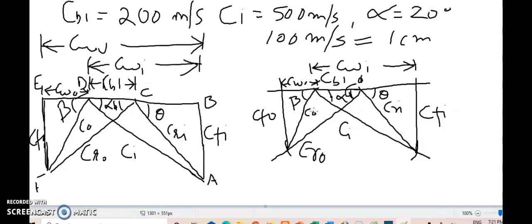So now we have all the data of the velocity triangles, inlet and outlet both, and such a method is known as construction method. By knowing all the velocities we can have blade efficiency, stage efficiency. Then obviously for the stage efficiency we need to have the nozzle data too, and the work done, axial thrust, power developed, everything can be calculated using this data.